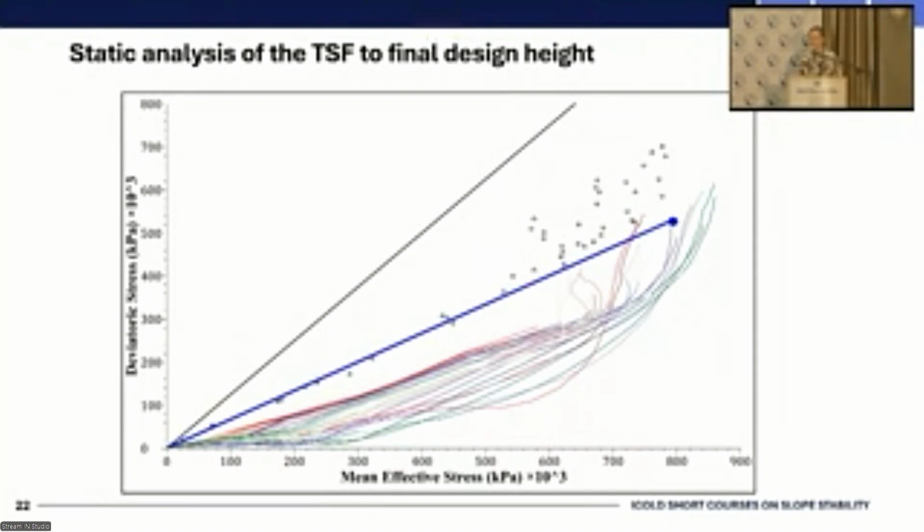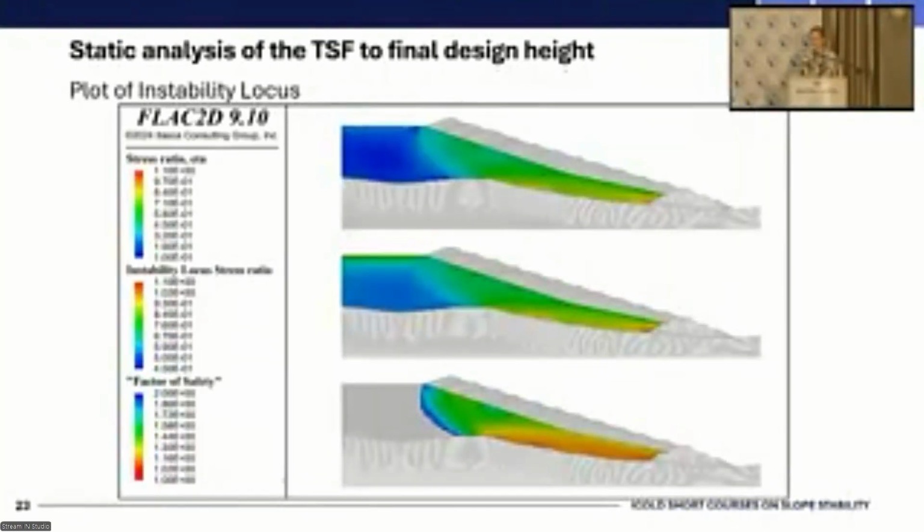If we, for example, look at that specific stress path, which has a stress ratio that is the gradient of that blue line, and then we look at its instability point, which has the stress ratio that is the gradient of the red line, and we look at the two in relation to each other, we could see how far undrained instability is from the current stress state.